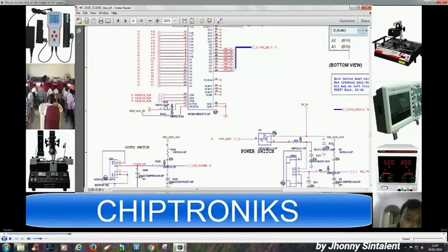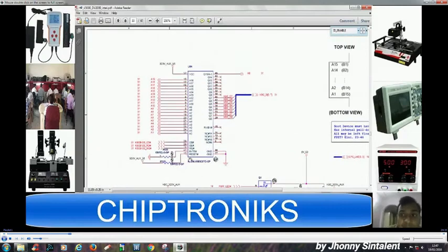If these three signals are there, that means EC is interacting with the BIOS interface. If the signals are not there, then EC is not interacting with the BIOS IC. In that case, the BIOS would be the problem, or the program inside the BIOS is the problem, or the EC inside the IO controller is the problem.